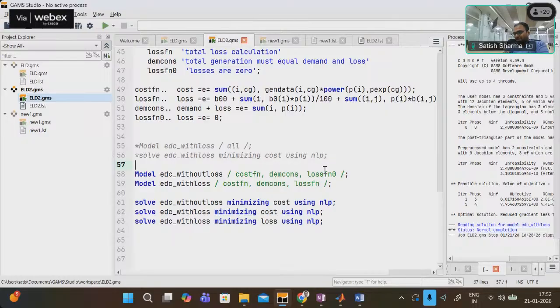My answer is both. Just yes and no, both. Yes is if a renewable can stick to its schedule, we can perform economic load dispatch, because the cost is zero. So the cost functions, you can say A, B, C, all are zero. We can simply assume an extra P renewable or P4, which is renewable generation, and we will put that in the equation.